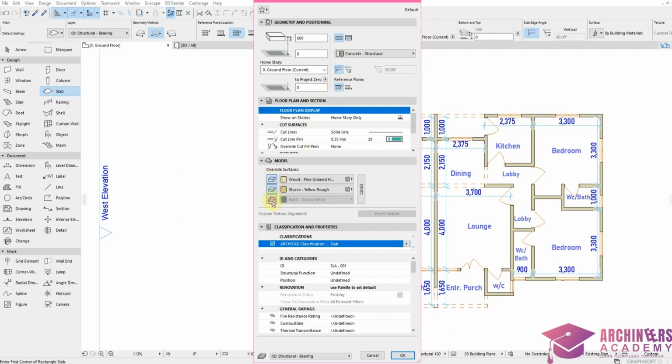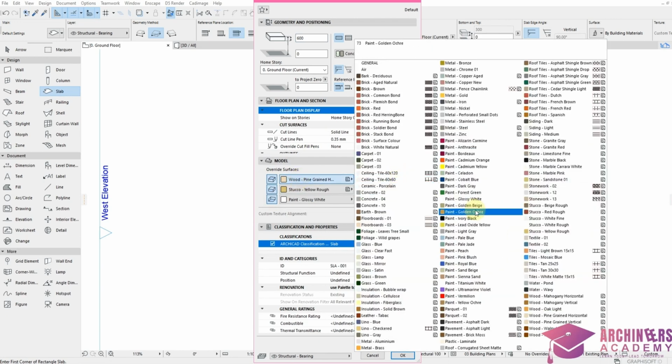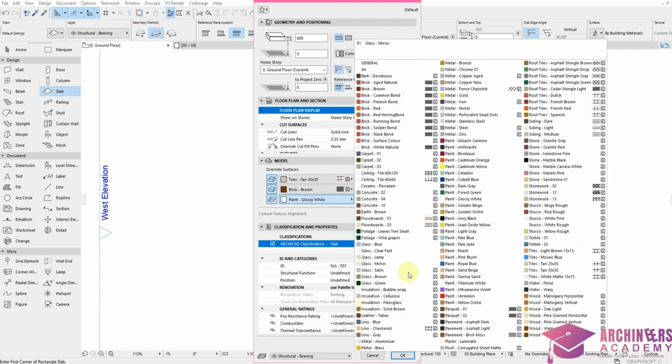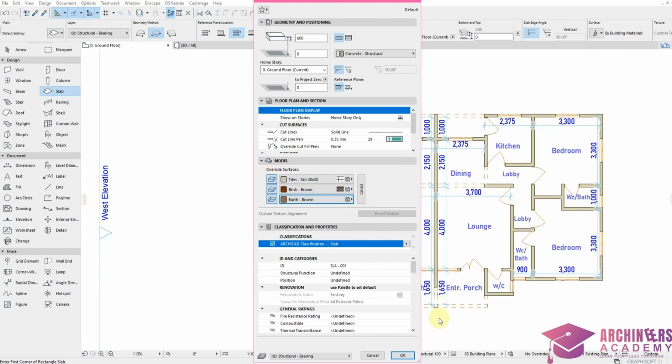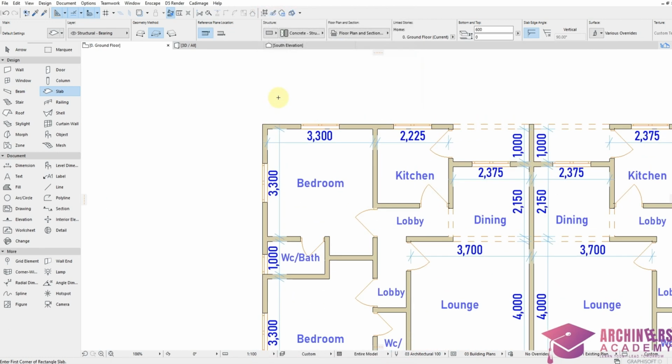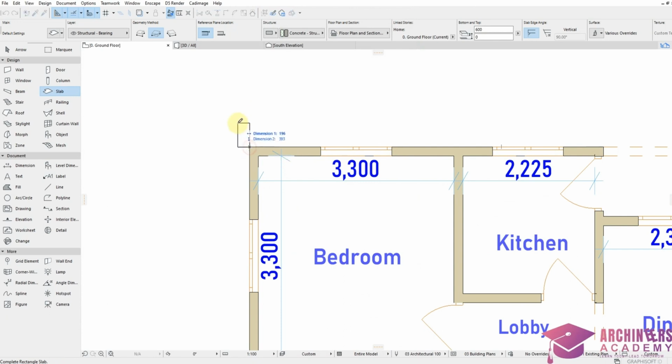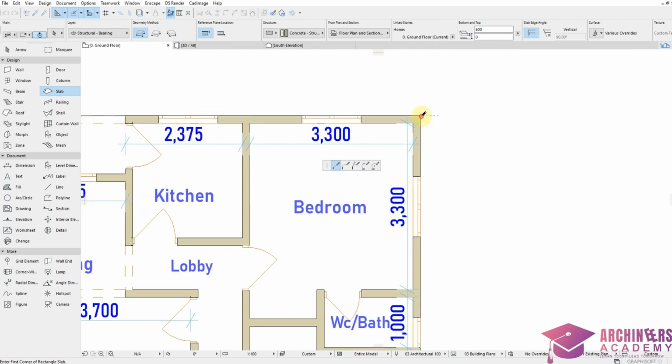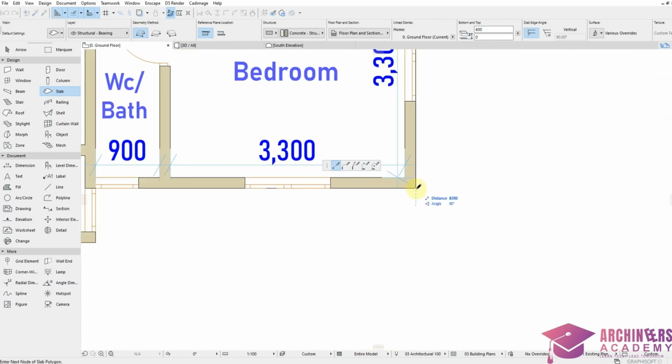Then the material we're going to use at the top will be a tiling material, so make use of tiles. Then you're making use of brick, and the under will be an earth material. So click OK. Then place our DPC, ensuring that the geometric method is polygonal, not rectangle, because the building is not rectangle. The building has multiple points, more than 4 points.